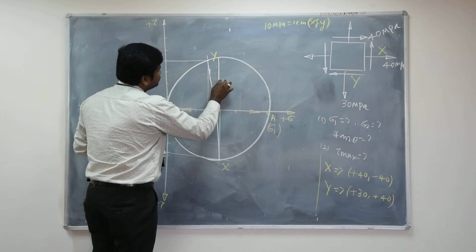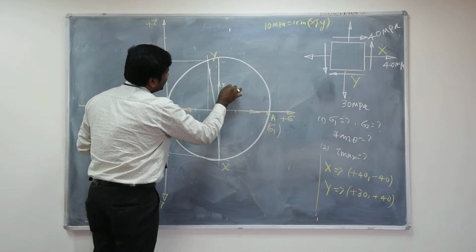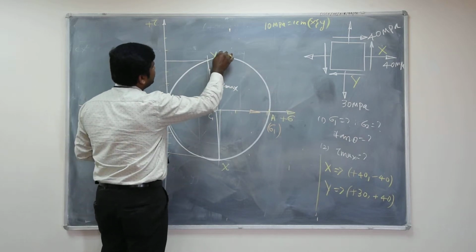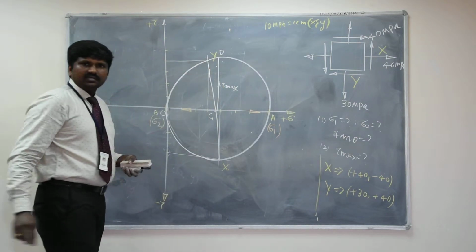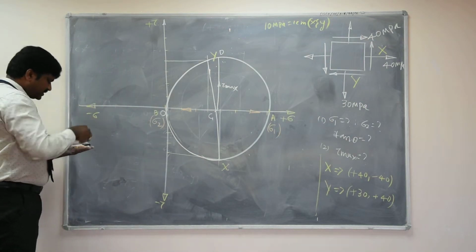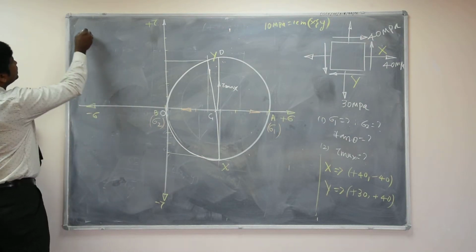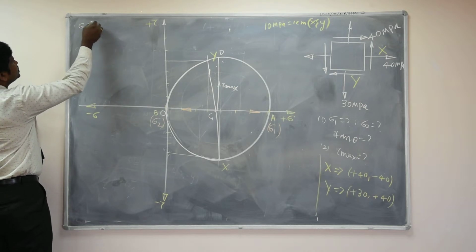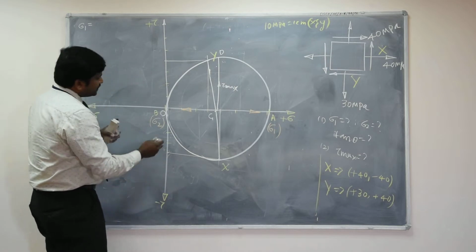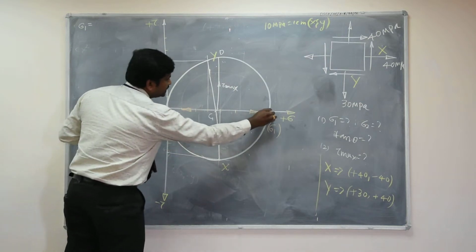Okay. So this is what is tau max. Let this point be D. Now to measure the distances, you can straight away measure directly. Say sigma 1 is equal to, what is sigma 1? It is the maximum principal stress. It is from O to A.